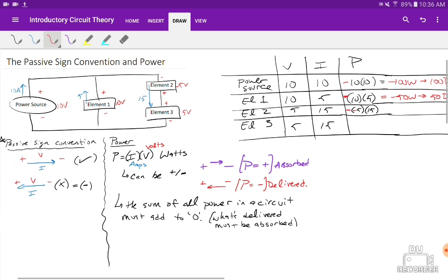All right. So you take the idea that because the passive sign convention is backward, I put a negative on the outside of things. And also, because I put a negative voltage in there, I have to put a negative voltage in my equation. So I really do end up with a double negative. They will cancel. And what I will end up with is 75 watts. And they're positive. Therefore, it's 75 absorbed. And that's how that has to be done. So I just wanted to show you guys that you'll be sticking in negatives past just seeing if the passive sign convention is obeyed properly.